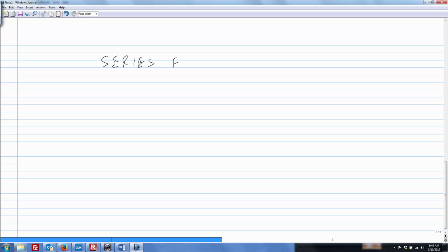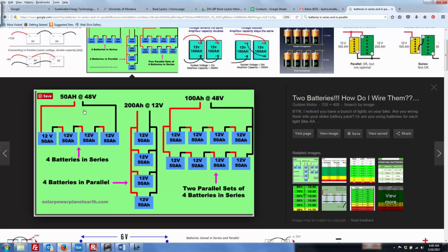energy, if we go back to our, that's always volts times amps times hours. Again, this is going to give us watt hours, because remember, volts times amps is watts. Let's take a look back at that period. So we're going to do 50 amp hours times 48 volts.